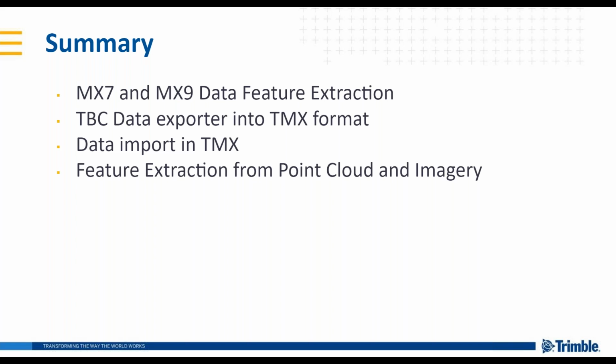A question: how to join the ridge lines at the corners and turnings. The ridge lines can be joined either by simply drawing a line that fills the gap between two lines, or you can start manipulating your data from the 2D view with the CAD tools.